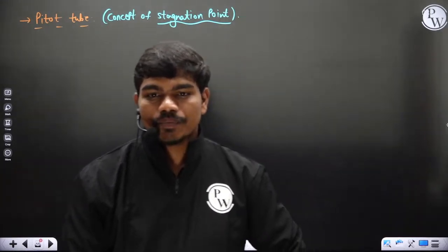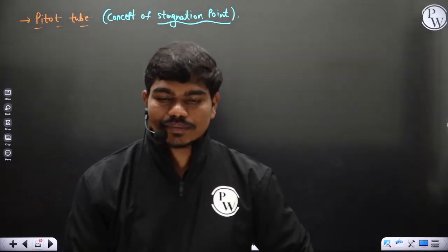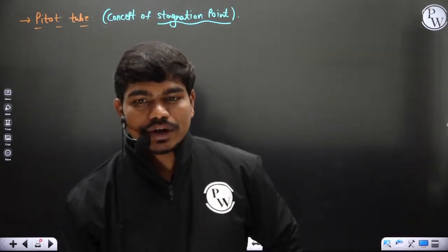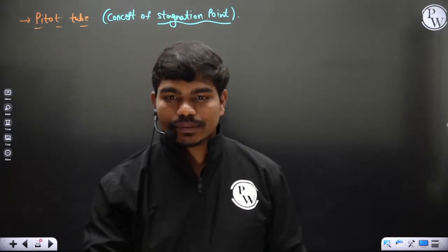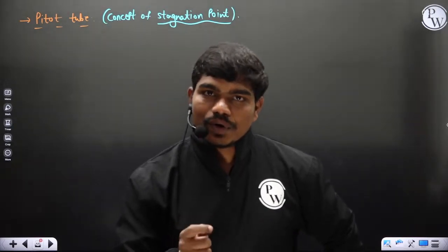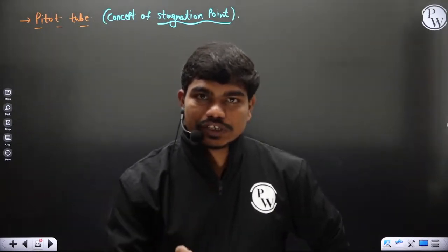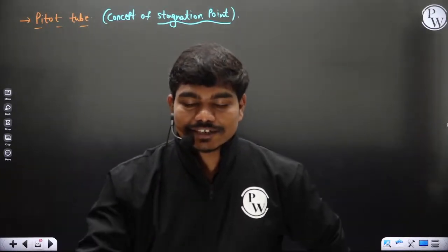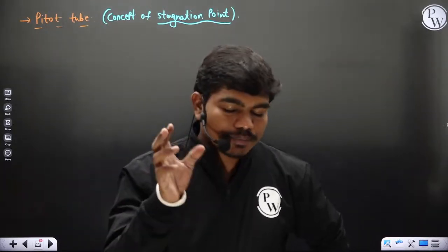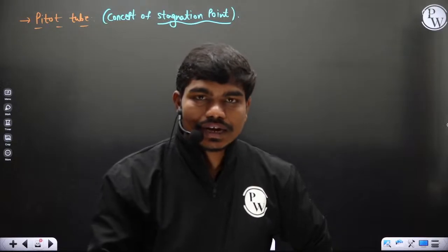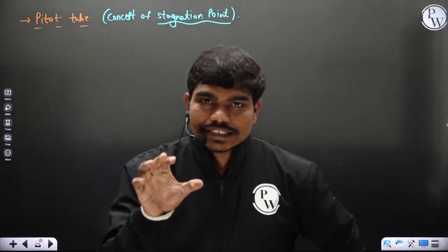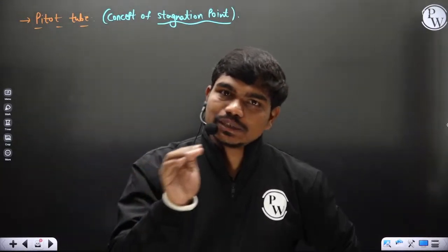So what happens is, temperature and pressure are connected for any system. Normally, in boiling, the formation of bubbles is not air bubbles, actually the fluid molecules get vaporized. Normally boiling point and pressure are very connected to each other from your basic thermodynamics, in the properties of substances. As pressure decreases, the boiling point also decreases. So corresponding to atmospheric temperature, there exists one particular saturation pressure.